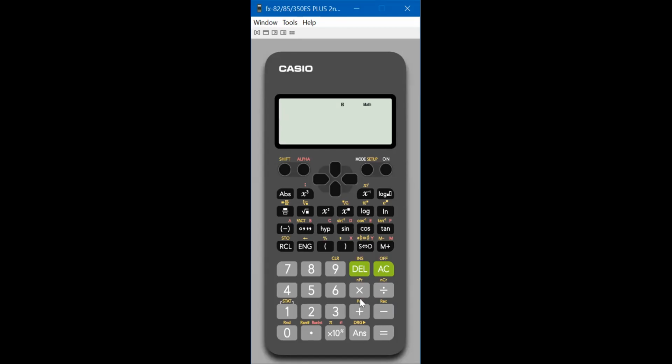Now because you have to convert into your polar form, you need to press shift and polar. Now when you have to write 6 plus j3, you write it like 6 comma 3, bracket close, and then equals. So this model gives you the value of theta and magnitude both at the same time. So here you can write it as 6.7 and angle 26.56.